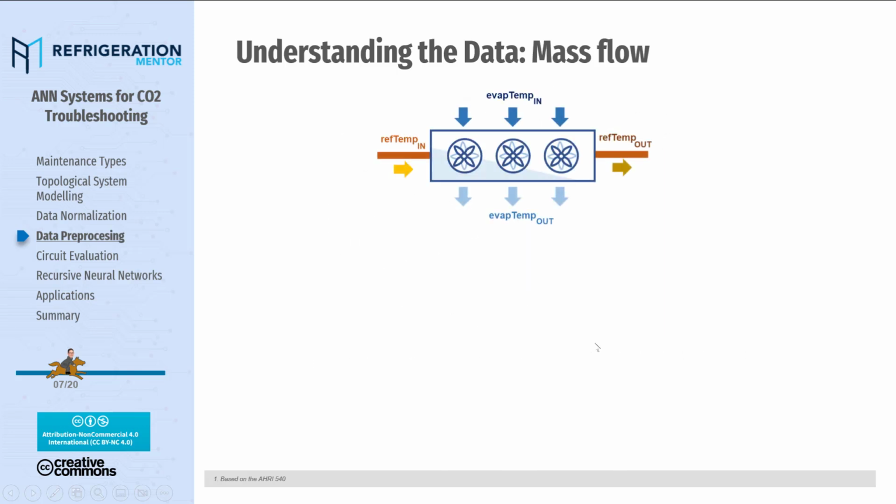From the evaporator side of view, this is an approach that can be used to calculate the mass flow required, where the heat gained by the refrigerant is equivalent to the one given by the air.